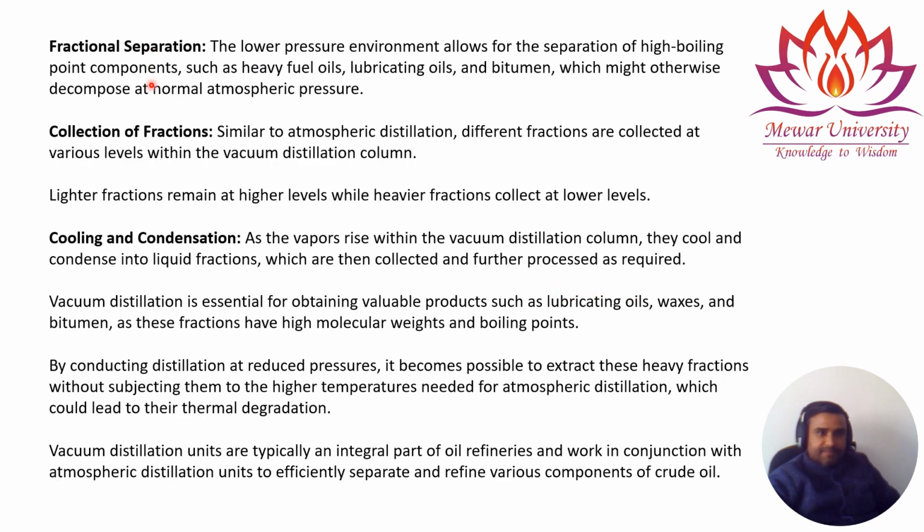So the next step is fractional separation. The lower pressure environment allows for the separation of high boiling point components such as heavy oil, lubricating oil and bitumen, which might otherwise decompose at normal atmospheric pressure. That's why fractional separation is done in the vacuum distillation column.